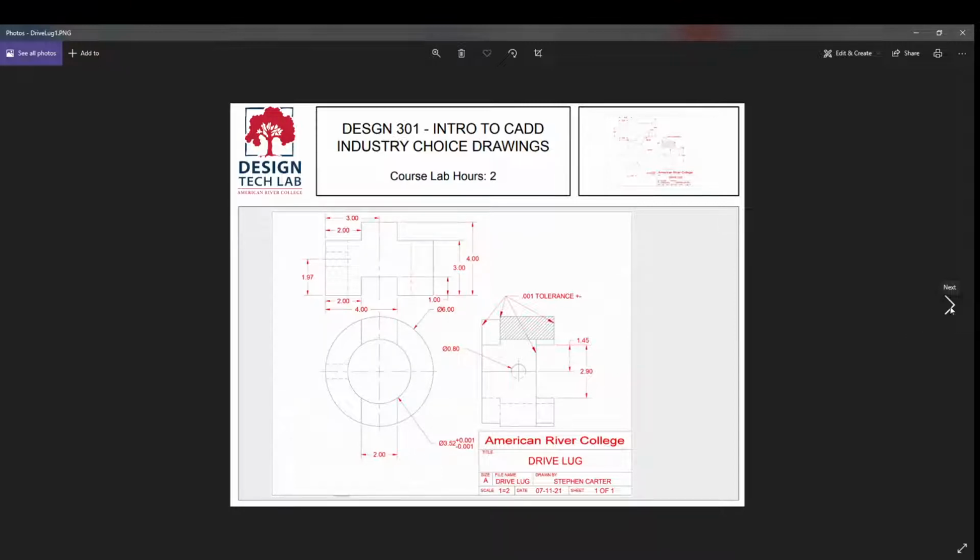Oh yeah, because what I did was I took the top projection, copied it over to the right quadrant, rotated it, and then I just intersected all my lines. Right, right. Which is essentially the quick way to do it. And then you just had to figure out what is where, right? Is this hidden? Is it visible? What's this one? You know, that's what comes up with those ones. Like having to cut that little piece out right there, and cut that little piece out, remember to do that. Yeah. So kind of neat.